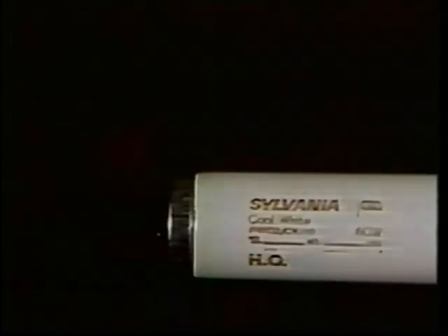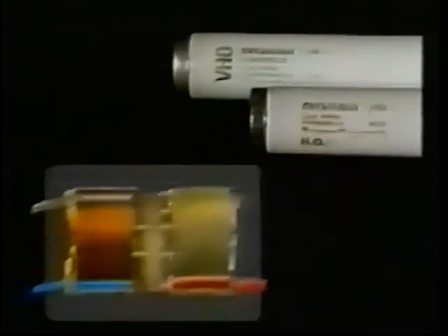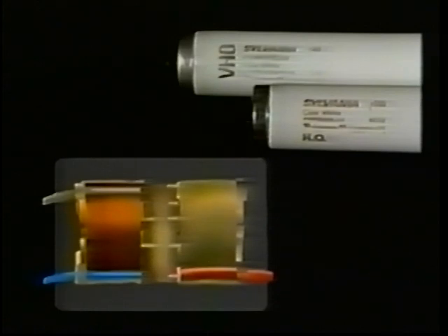Today, the rapid starts are one of the most commonly used fluorescents. The rapid start fluorescent product line also includes the high output, or HO lamps, and the very high output, or VHO lamps. These use higher currents in order to increase efficiency. They both require special construction to allow for these higher operating currents and pressures, as well as specially designed ballasts to deliver the proper higher voltages.